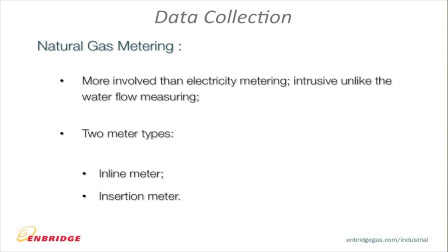I will be the first one to tell you that it's more involved than electricity metering. It is more intrusive than the water metering, definitely. And there's 2 meter types. That's all you can essentially do today. There's an inline meter and there's an insertion meter. There is such a thing as an ultrasonic flow meter, but unless you have the line in hundreds of psi of pressure, you will probably not get anywhere with it. And if you do, let me know, because that's valuable information.